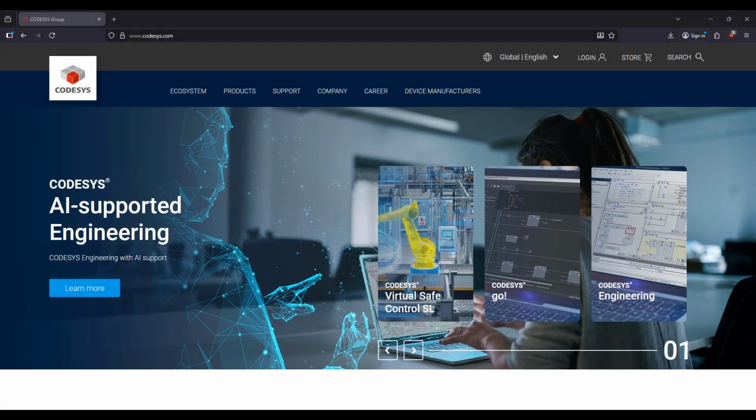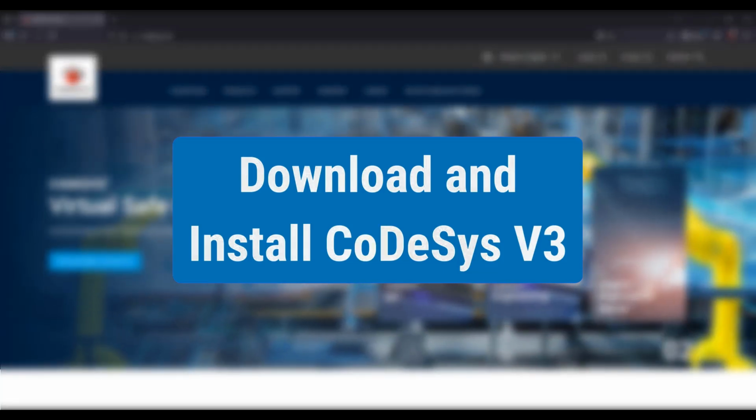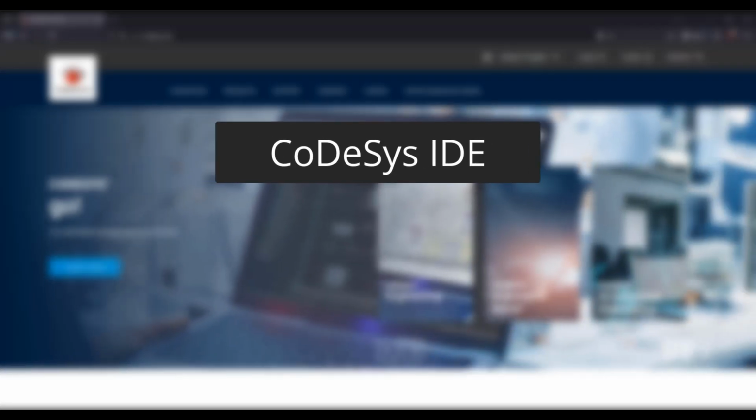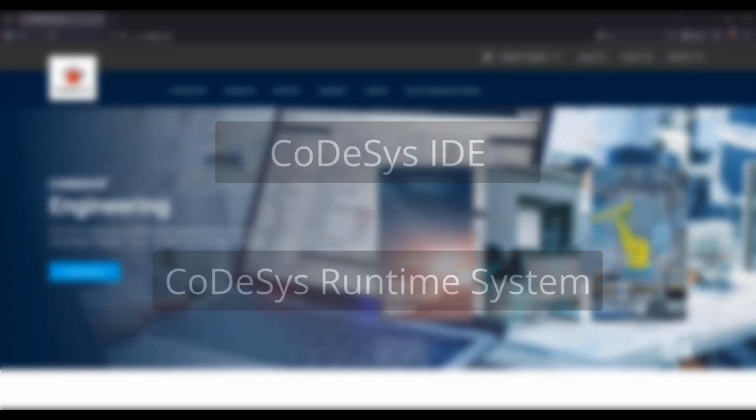In this video, I'm going to show you how to download and install CoDeSys v3. That is the industry standard IEC 61131-3 development environment. When downloading CoDeSys v3, you get both the development system, the IDE, and the CoDeSys control runtime system. With these two components, you can both develop your own PLC application and also test it and simulate it within your Windows PC.